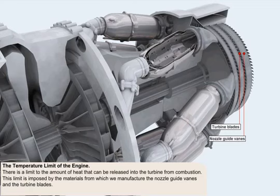This limit is imposed by the materials from which we manufacture the nozzle guide vanes and the turbine blades. The Germans' inability to produce materials which could withstand the heat of the gas stream was the main problem with the early German gas turbine engines. Because of the poor materials used in the turbine assemblies, the engines would only run for between 10 to 20 hours before the turbine blades suffered meltdown and engine disintegration commenced, usually in a quite catastrophic fashion.